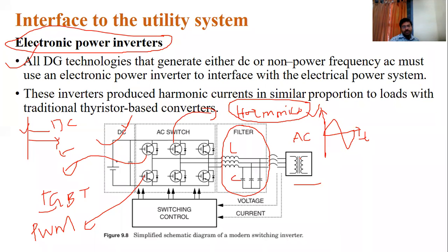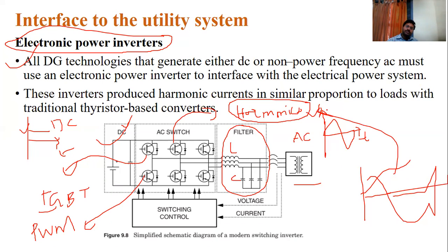While we are using solar energy to improve the power quality, yes, solar energy will definitely improve power quality. But even so, in that process you may get some harmonics in the system. You know the main problem with using electronic switches in the power system: they draw the current in a non-linear form, just like this, and that may also lead to harmonics.